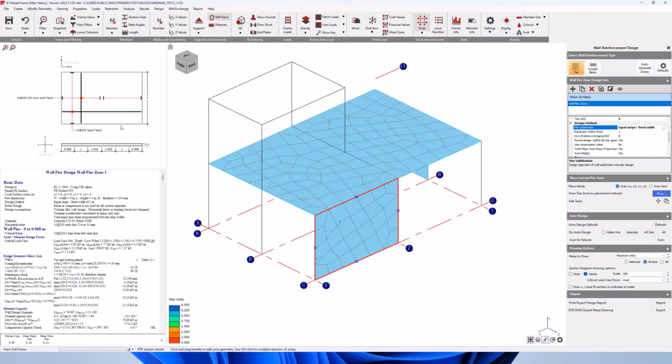We can see that even though we use the default 1 meter fixed strips, the outer strips are slightly narrower, while the innermost strips are somewhat wider than 1 meter. This is because the program chooses sensible design strip widths with rounding to the rebar spacing midpoints.